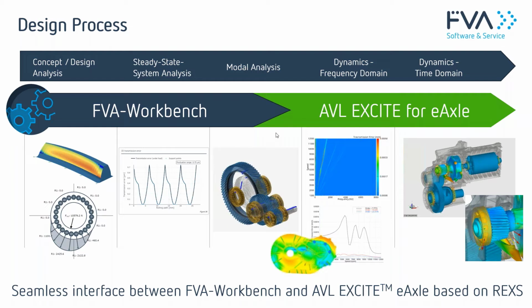You can now calculate the critical frequencies, but you do not only get the frequencies, you get all the dynamic loads which are excited when you are close to an eigenfrequency, and you also get the behavior of your housing, so which part of the housing vibrates at which frequency and so on.